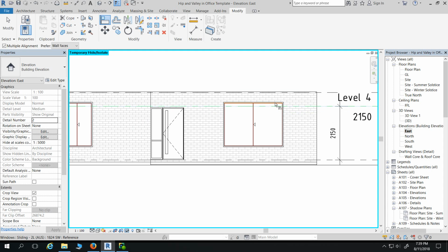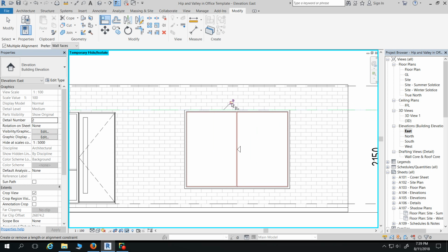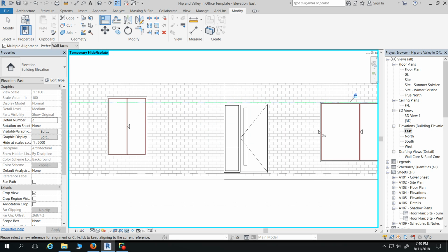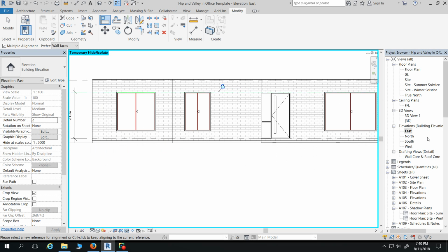So it's just a case of then selecting your level, coming in and clicking, and then this is an important tip, hit the padlock, because that then will constrain it to the level. So if the level moves, the windows go with it. I wouldn't do the doors because a door needs to actually change the physical height of the door if they move. So I wouldn't do the doors. So it's just a case of going along and aligning them in all the elevations.